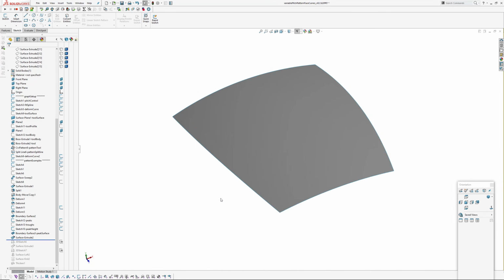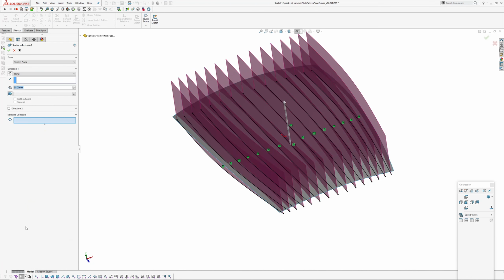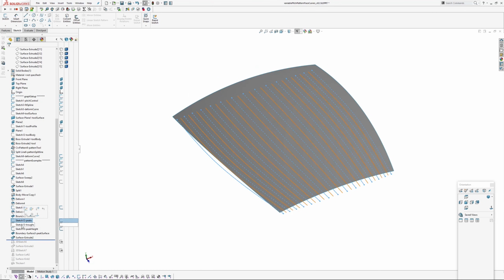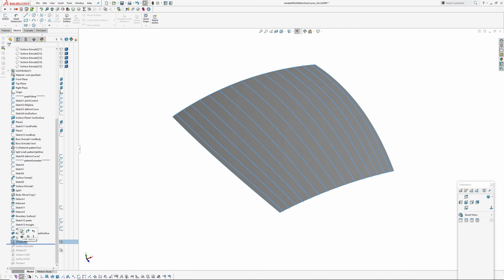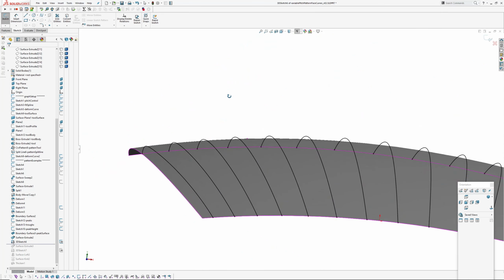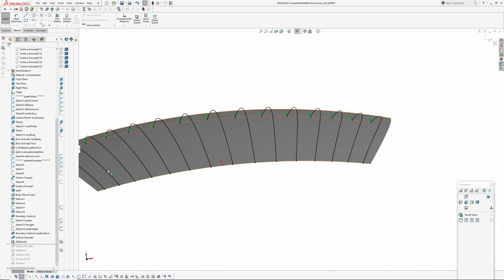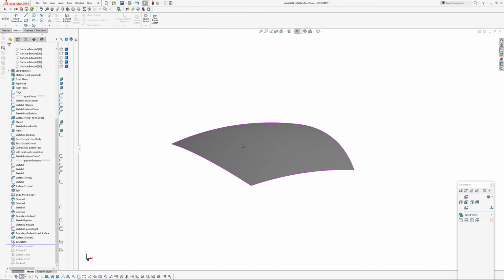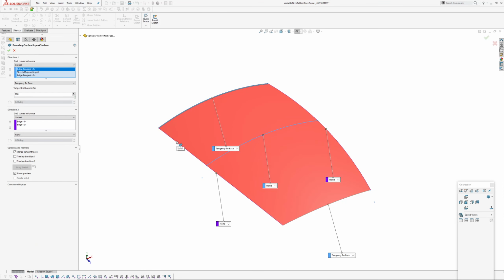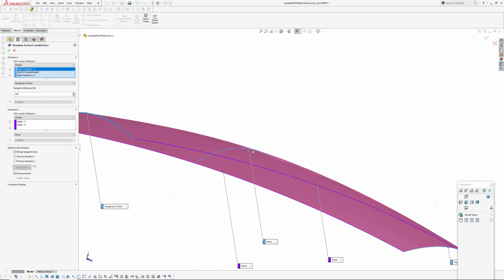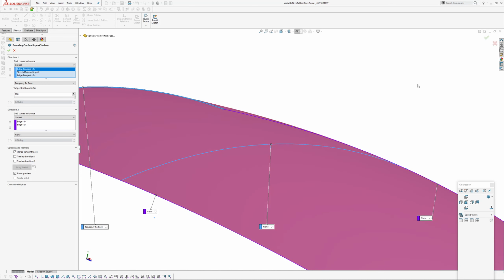To get those curves on the 3D surface, what I've done is extrude surface. In this case, those are the peaks, and then done the same with the troughs, and created a 3D sketch to get those curves in 3D space. So these are the peaks, as you can see, and they intersect here with my peak surface, which is built in a similar way to the first example, using the side boundaries of the split surface and then a cross curve across here to set the height above. So that's the peaks and that's the troughs underneath.